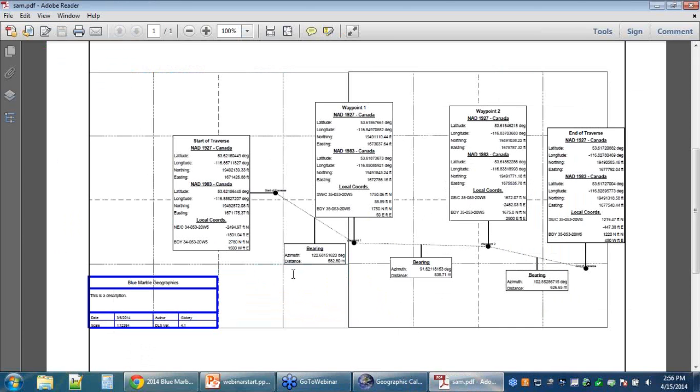Within the context of our townships there, you'll see each of those points has the NAD 27, NAD 83, and the local coordinates displayed for each of those local points. Right now, if you were looking for the section numbers, the townships, the range, that stuff, you'd be looking down in those strings for the local coordinates to find that. I know that's not the cleanest labeling. If you'd like to actually have the section numbers, the townships, and such on the map, that's the kind of thing that we're looking for feedback on.